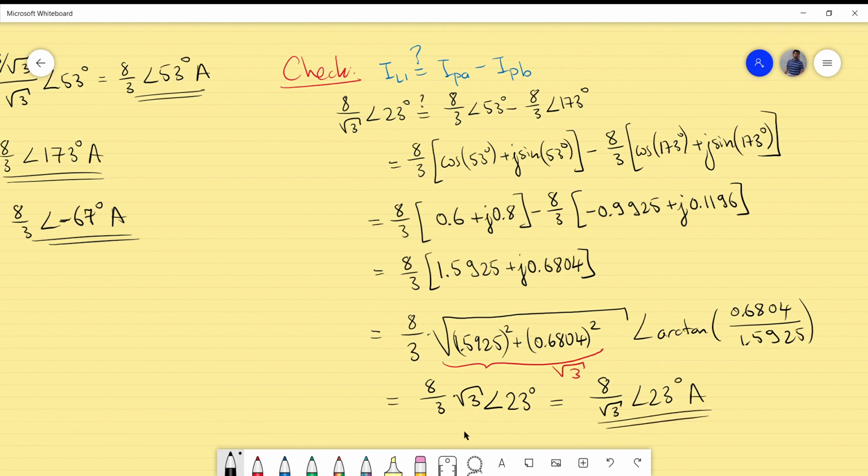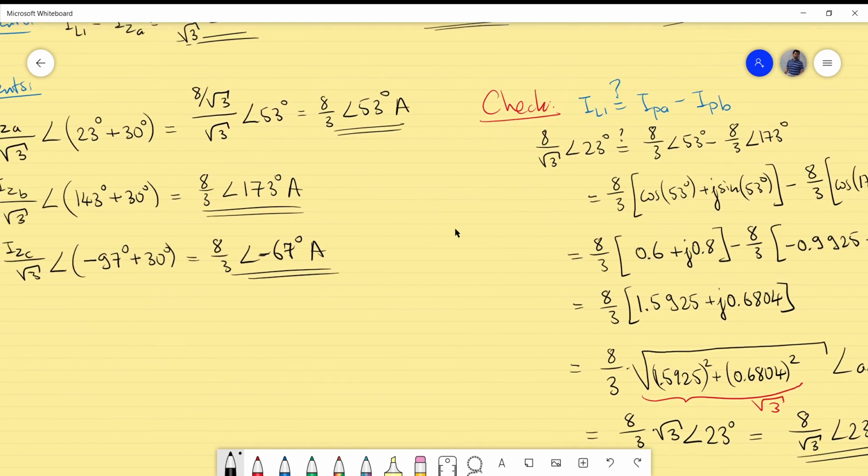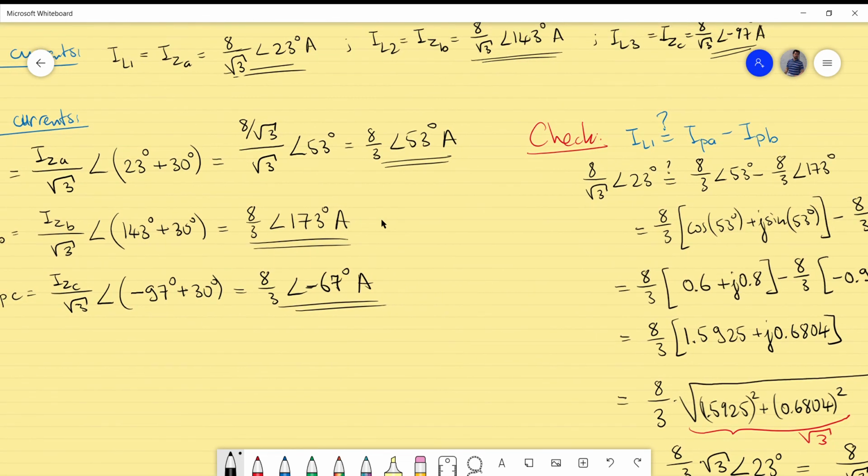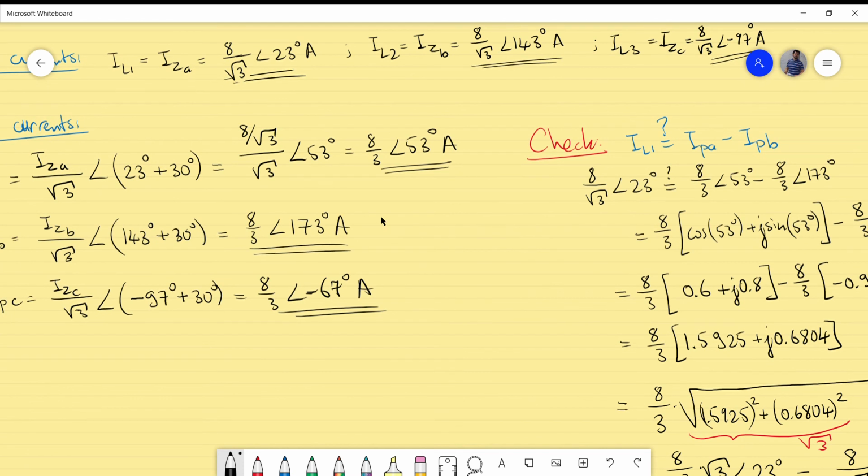And look at it, you have exactly the same expression for the current, using the subtraction here, and you have the line current IL also produced. So we made a check such that we can verify that this formula also is correct. So remember, in this example, we have used a specific configuration for the delta source, and that will allow us to use the formulas for the load currents and the load voltages we have used in this example. So be careful, don't use this just blindly. Look at your configuration for your source and then decide if you can use it or have to make an addition using a minus sign for the load voltage and also for the load currents.